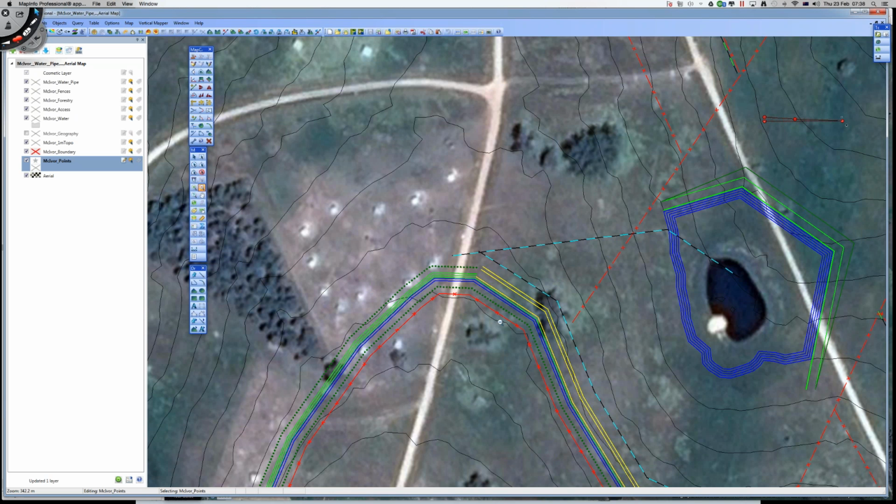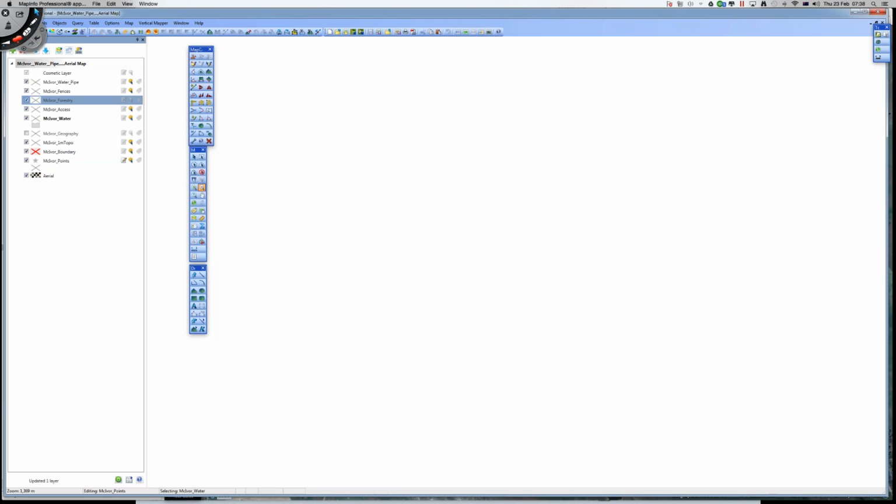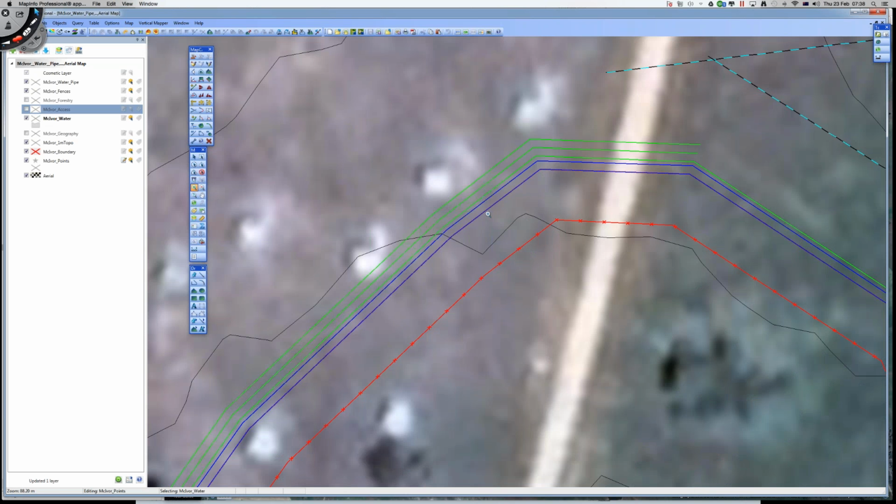So once we selected this first line, we made a line like this one here. Sorry, I'm just going to zoom out a bit. So we selected that line. I'll turn off those other layers for a moment, just so we get a little less noise. And then, in order to create the actual size of the embankment, we then offset the ditch as it is.